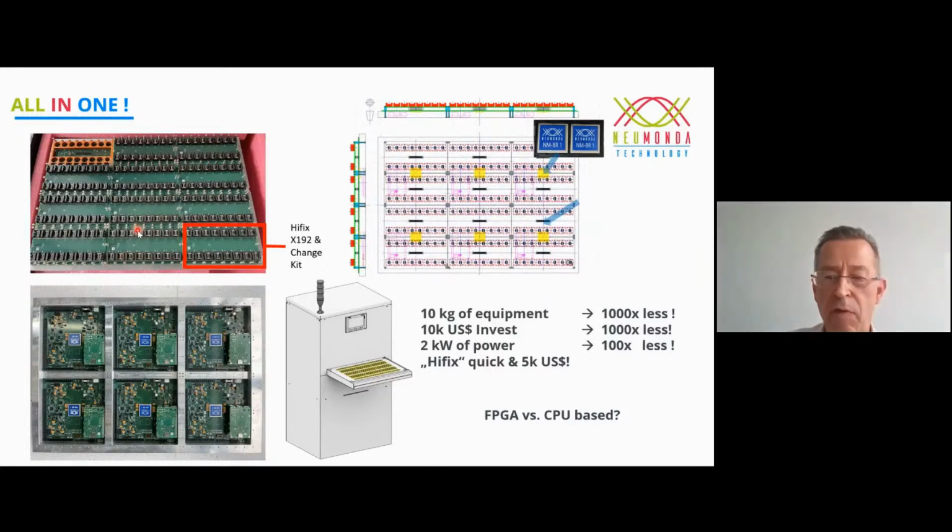A more customer application realistic environment. You mount several on a board, and then you can use the infrastructure which exists today for burn-in. Automatic loading, automatic unloading, analysis of your test results, when are the sockets degrading, when you need to replace it. Instead of a $250,000 hifix, our hifix is now this printed circuit board. It can be designed very quickly, 3-4 weeks, $5,000 development cost, very cheap.